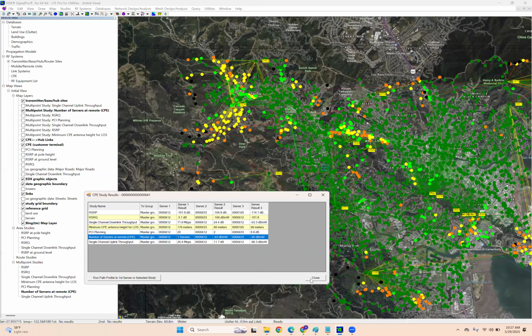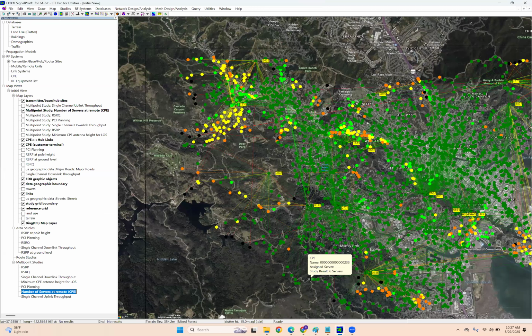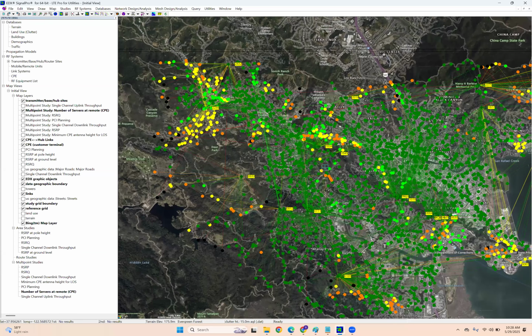And then another redundancy use case that we've been asked about and that we've seen folks looking at is to look at the possible connections between these base stations. So whether we're talking about LTE equipment or the GEMDS equipment or what have you, oftentimes if the backhaul fails for one of these sites, it can potentially store and forward its messages through another site, especially if we're setting these things up for distribution equipment.